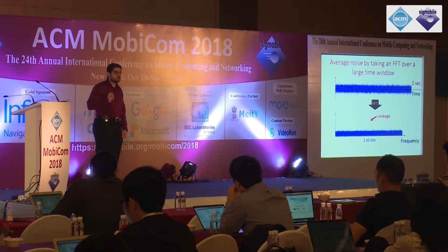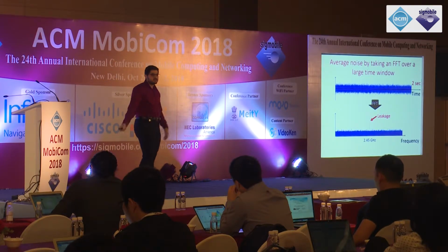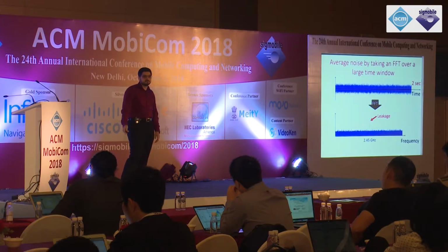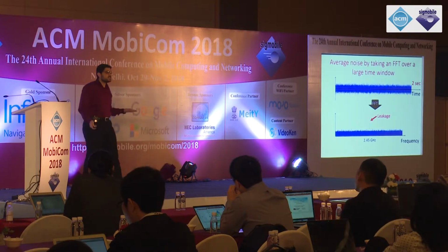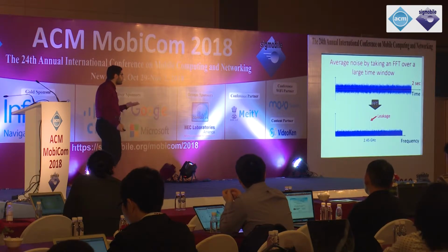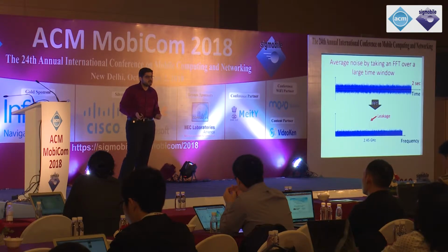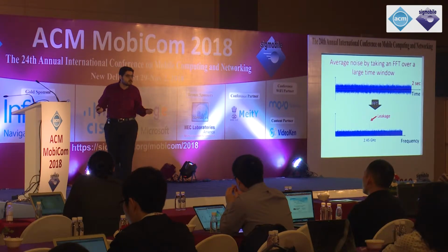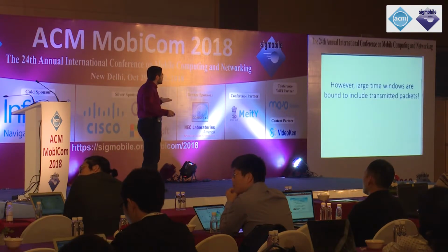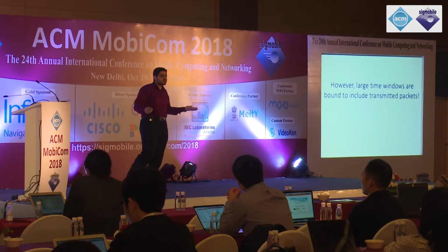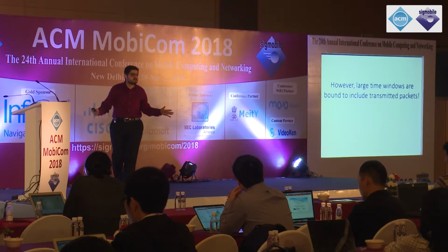Great. So are we done? Do we just take a large FFT, we see who's there, and we're done? Turns out we're not. Because what we really care about is to know who's listening when we're actually transmitting something, right? If we're not transmitting something, who cares? And it turns out in typical networks like Wi-Fi, it's very hard to find a 1 or 2 seconds window where there's no transmissions whatsoever.